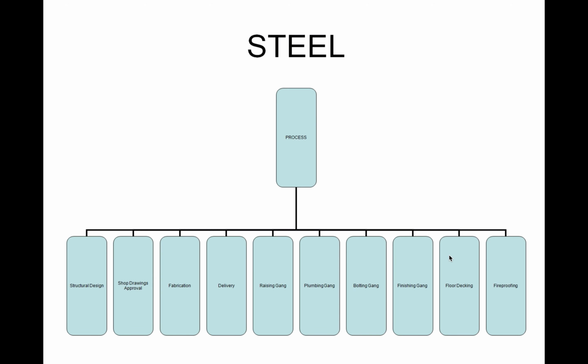And then there's the fireproofing of all this steel, because that's part of the code. All right, steel when it gets hot melts, because that's how it comes out of its raw material. And you don't want a building that catches fire and have its structural components start melting with the heat. So what we do is we usually cover it with some form of fireproofing, which is usually in the form of concrete or shotcrete.